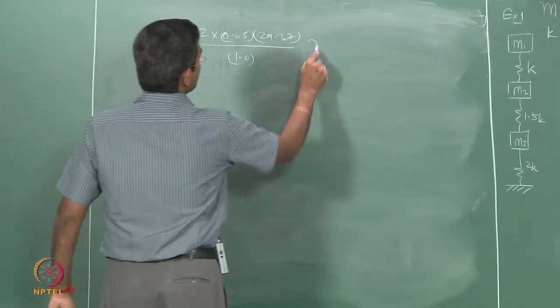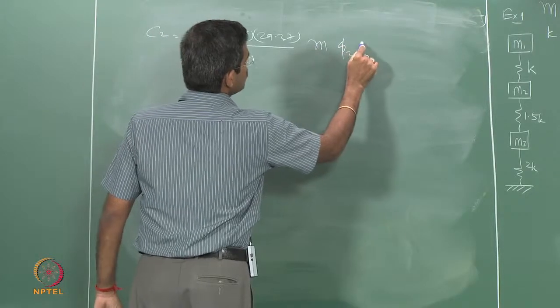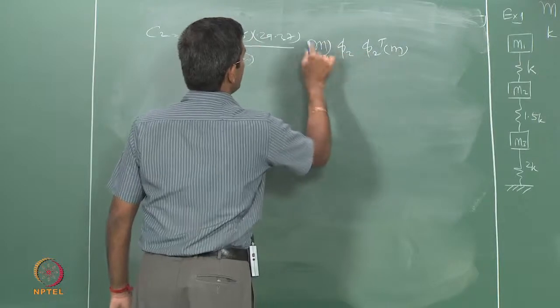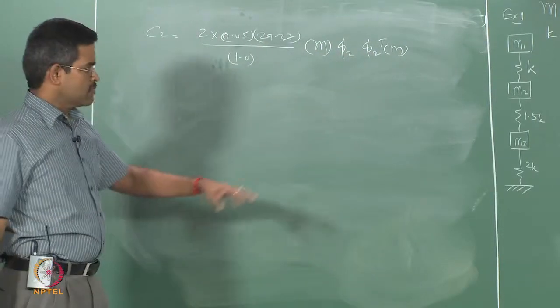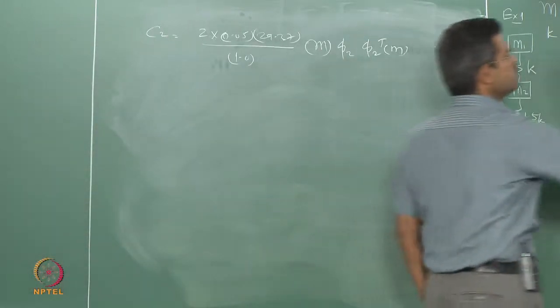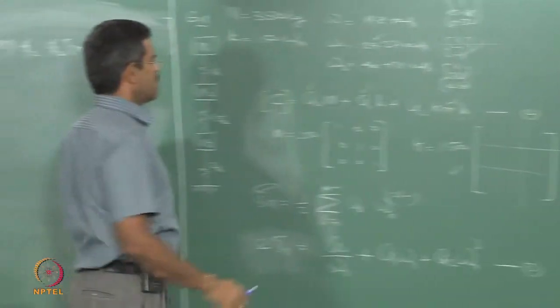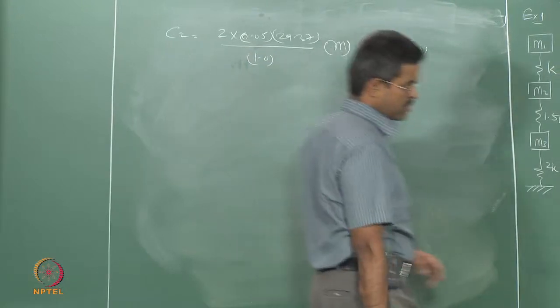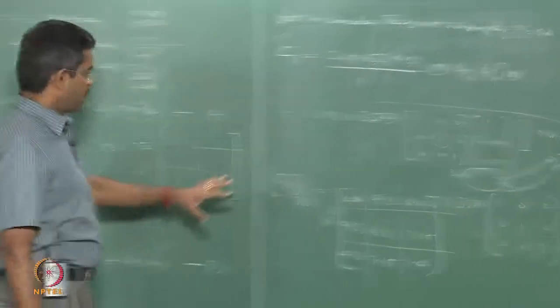1 multiplied by m phi 2 transpose, yeah. So, I have all the values because phi 2 I know here, phi 2 transpose I can find, mass matrix available here. I will pre-multiply proportional to 3500 in both the cases as I did here, get the value, and I am now writing C2.